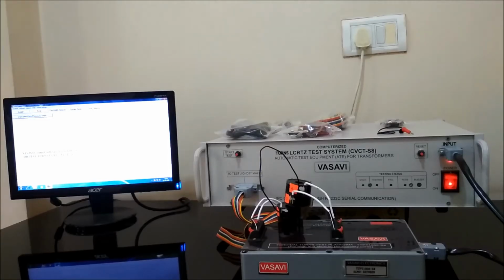You are now watching the demonstration video of the computerized TURNS-CVCT-S test system, model CVCT-S4. This is a new test instrument that can test turns, inductance, and RDC for current transformers, and it can test up to 4 CTs at a time.